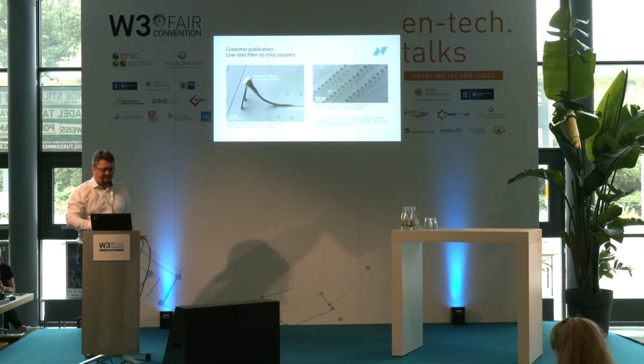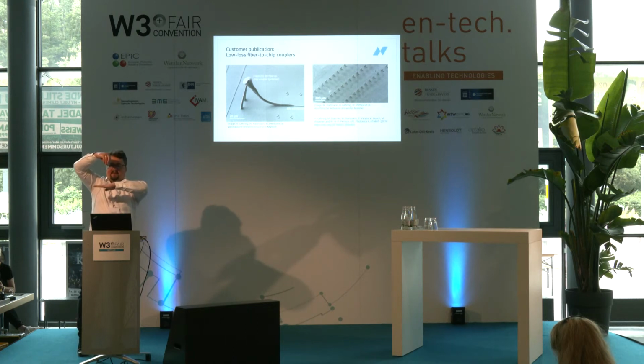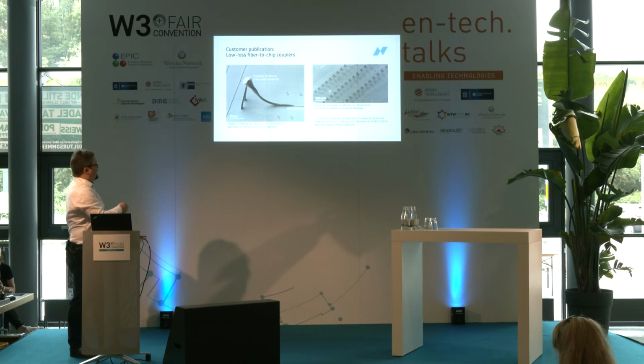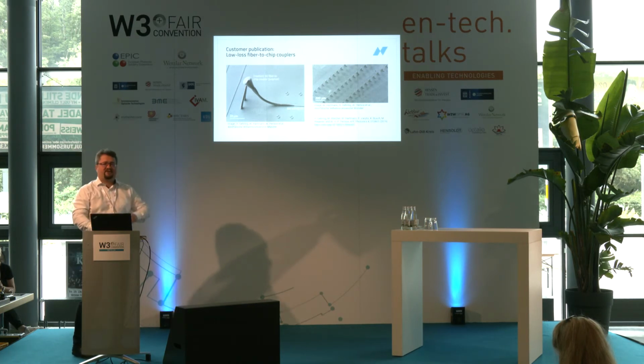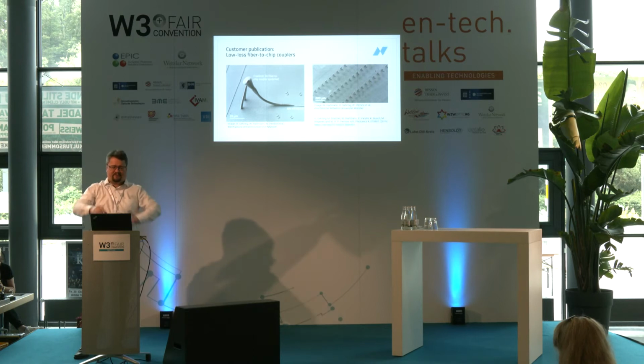You can drive this even further and now print complex micro-optical assemblies to really guide the light where it's supposed to go. Now we're back to the situation where the fiber comes from out of plane. So the fiber comes roughly from the top, and the waveguides are in plane, and they have the situation that they don't just have one fiber, but a whole array of fibers, and they want to couple the signal from the whole array of fibers into their photonic chip.